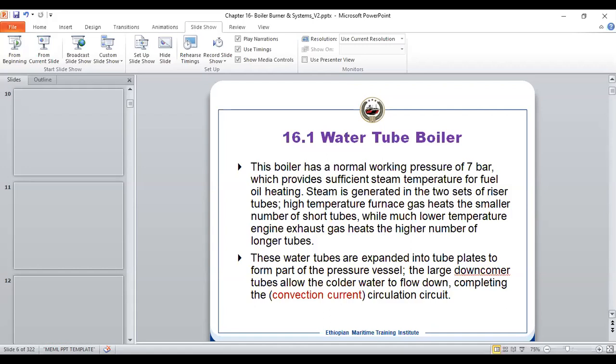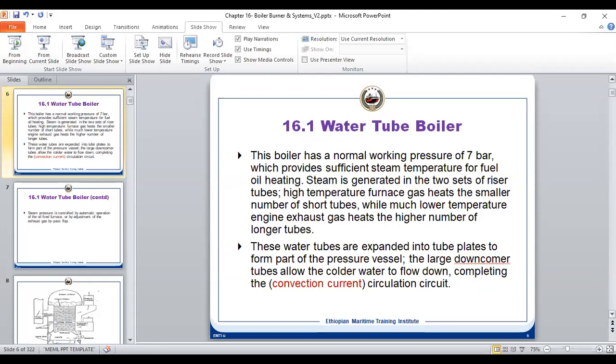Yeah, but it says efficiency composition. I don't know why. It says so on the point. It's less efficient composition. No, it's not less efficient combustion. It's less efficient boiler. Maybe that's a mistype, which we can correct. The combustion, we can have the same burner in both the boilers, but the smoke tube boiler itself is less efficient as compared to a water tube. So that would be a mistype. It's not the combustion; it's the boiler, the entire boiler itself.